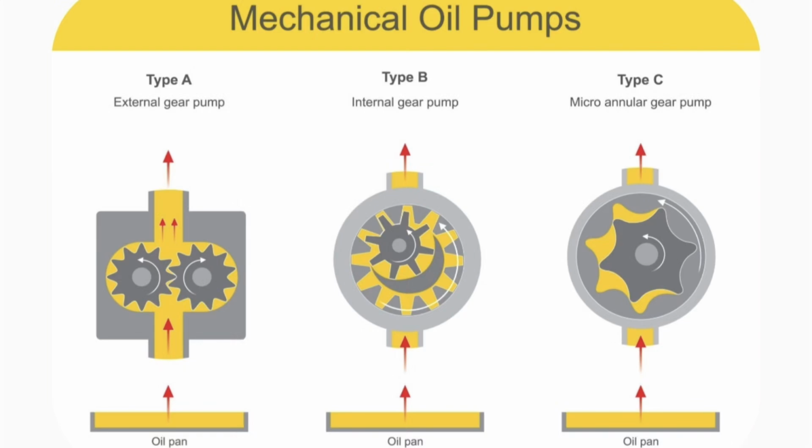How hydraulic pumps work. Operating principle. All positive displacement hydraulic pumps operate on a simple two-step suction and discharge cycle. 1. Suction phase, inlet. Expanding internal volume creates a partial vacuum at the pump inlet, causing atmospheric pressure to force hydraulic fluid from the reservoir into the pump chamber. 2. Discharge phase, outlet. As the internal mechanism rotates or reciprocates, the chamber volume contracts, trapping the fluid and forcing it out into the system under pressure.